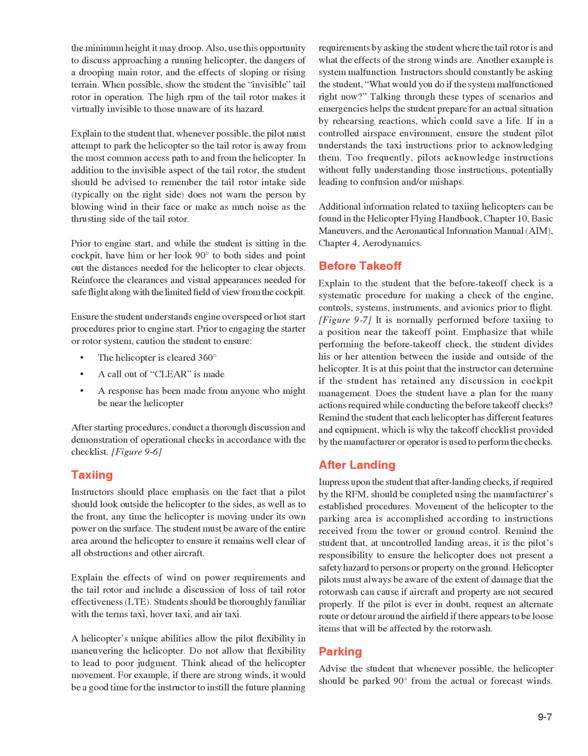Emphasize that while performing the before takeoff check, the student divides his or her attention between the inside and outside of the helicopter. It is at this point that the instructor can determine if the student has retained any discussion in cockpit management. Does the student have a plan for the many actions required while conducting the before takeoff checks? Remind the student that each helicopter has different features and equipment, which is why the takeoff checklist provided by the manufacturer or operator is used to perform the checks.